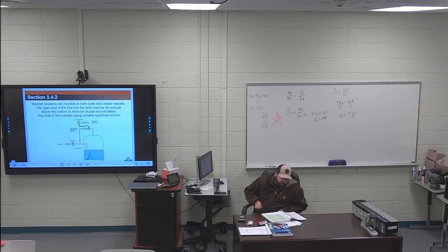Page 30, the sentence that splits the columns and the one after it are highlighted as an online test question. The height of an accidental hole in the bubbler pipe is inversely proportional to the output of the level transmitter. In other words, the higher the hole is on the pipe, the lower the level indication for the tank. I wrote below that, pinholes are bad for bubblers.